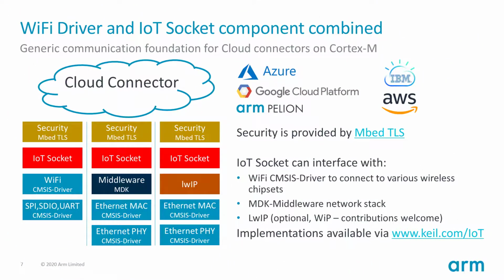You might ask, why is this important? Can't I just use my own custom driver that is provided by my silicon vendor, together with some code that I get on the internet? The great benefit of the CMSIS-Driver approach is that you can easily create variants of your application or switch to a different target while the project is running.